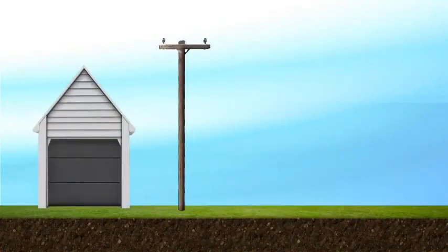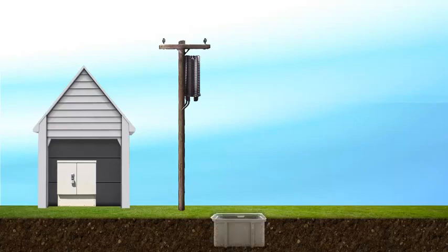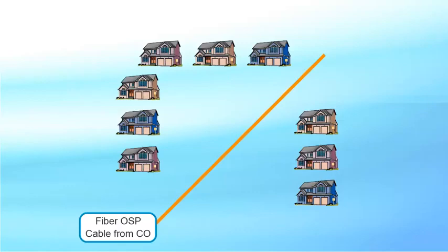There are many possible component choices for building FTTx networks. The most cost-effective option can only be determined by applying the different engineering rules and constraints for each approach to the actual geography of the region. Expanding outwards from the central office towards the subscriber, the key FTTx infrastructure elements are the feeder cable, which includes a large-size optical cable and supporting infrastructure, for example, ducting or poles.